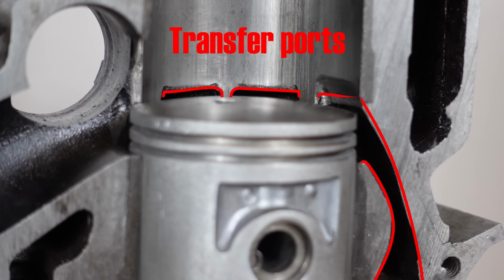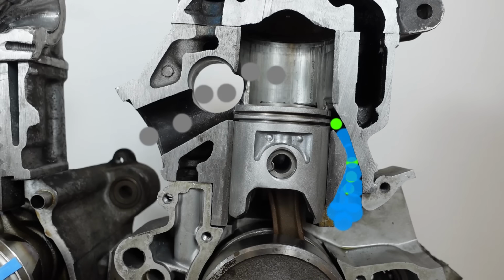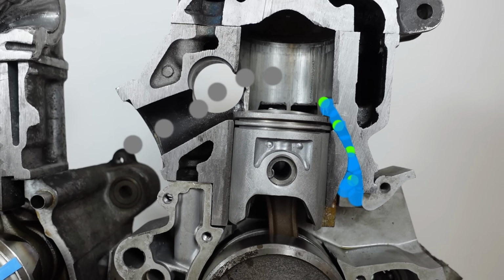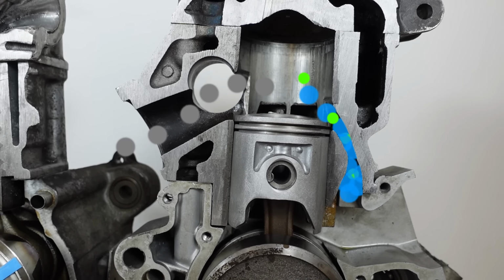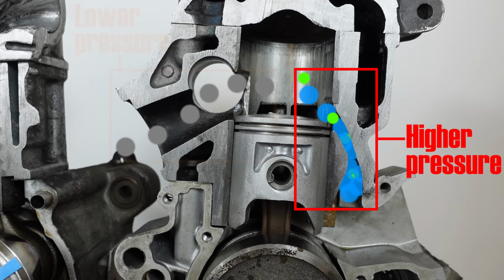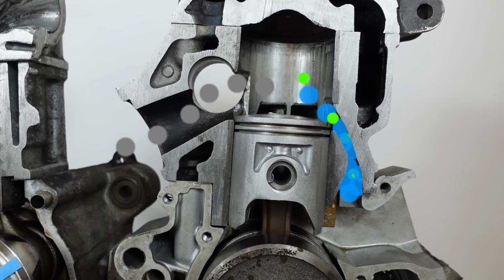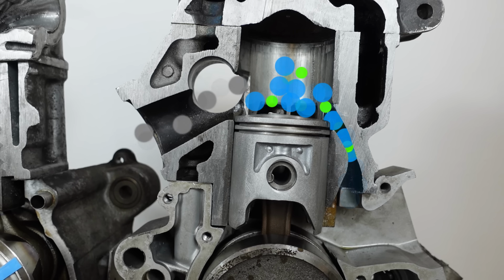which then allow the compressed air-fuel mixture from below the piston to be transferred above the piston. The pressure in the cylinder has already decreased substantially because much of the exhaust gas has been allowed to escape through the exhaust port. This means that the compressed air-fuel mixture coming out the transfer port is actually at a higher pressure than the remaining exhaust gases in the cylinder, which means that as the air-fuel mix enters the cylinder, it helps to push out the last of the remaining exhaust gases.